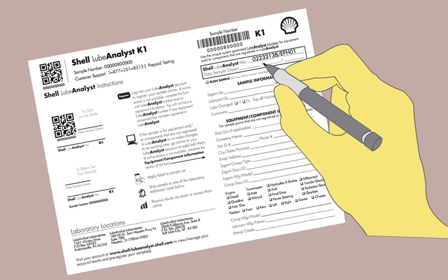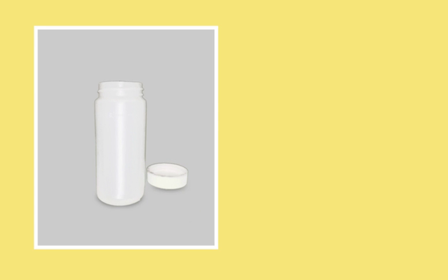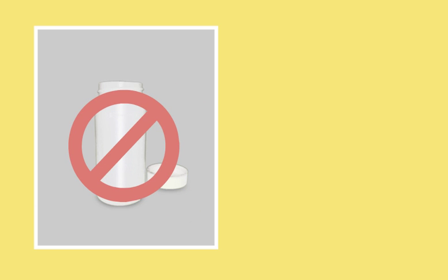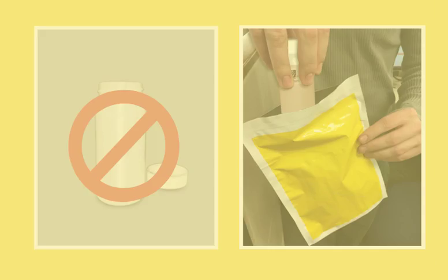Make sure the checkbook page is properly dated, has the miles since the previous PM and the oil type, and that any unusual operating situation is noted. Also, remember to carefully manage the sample container and its contents. Don't let the bottle sit open and get dirty. This could skew the lab results. You should send the sample to the lab immediately. Because an oil sample indicates the condition of the oil and the equipment at the time it's taken, it's important to promptly send it in for analysis.